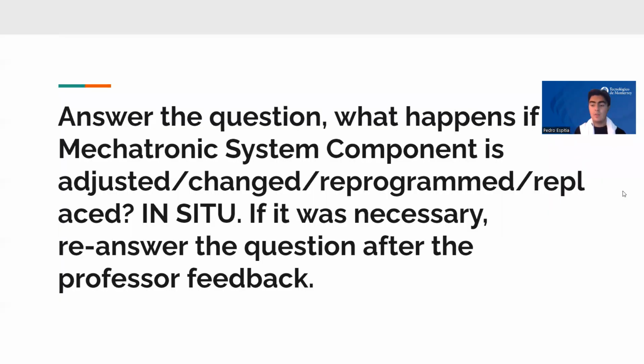And at the end, our teacher said that we have to explain the different questions that he tells us in class. In my case, it was explaining how the ultrasonic sensor works. I say that the brown cable connects to the 24 volt part of the PLC, sorry, the cabinet, and the blue cable goes to the neutral zone. We take the normally open contact to the free clamp, and the free clamp connects to the relay. It causes the 24 volt signal to convert to a 110 volt signal, which is the necessary voltage to send a signal from the ultrasonic sensor.